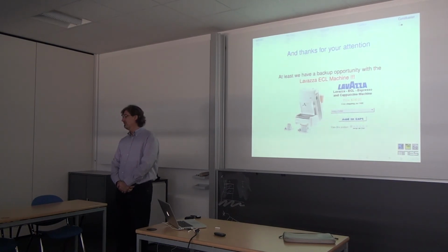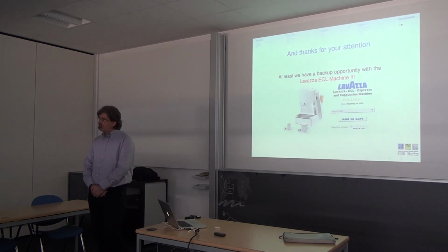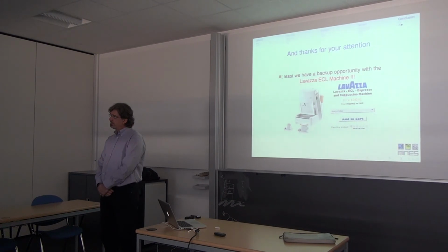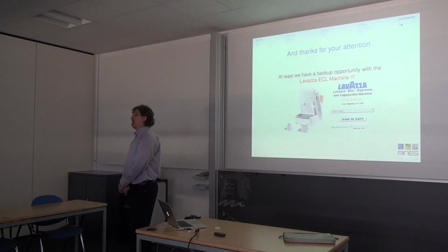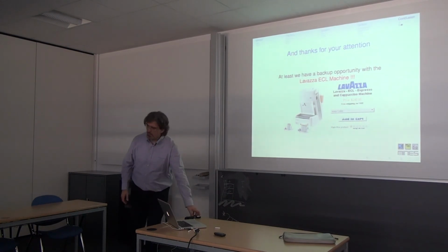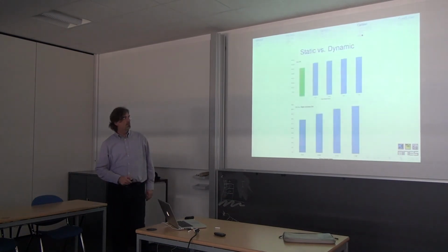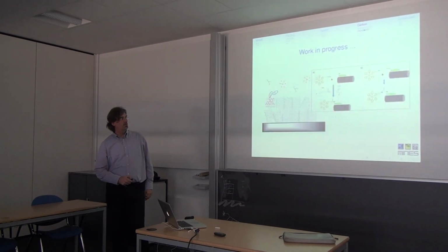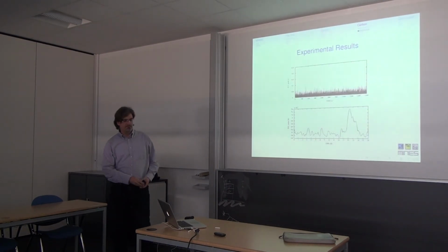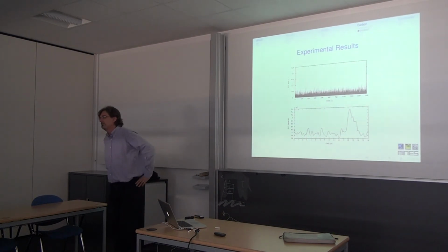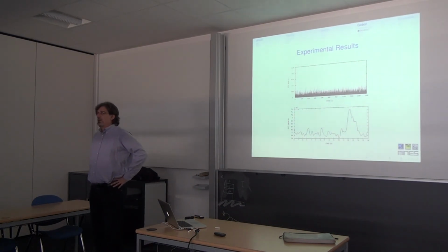Yes, please. When you do the measurement, you detect the intensity. But do you integrate over the signal? You say it comes at minus 0.8 volts. So do you only take the maximum peak, or do you integrate the signal which you get around 0.8 volts? Because for your carbon nanotube electrodes, I think you may have differences in the work function. And when the work function changes, you may have a signal which is broader in some cases and on a smaller voltage area in other cases. So maybe you should take the integrated signal.